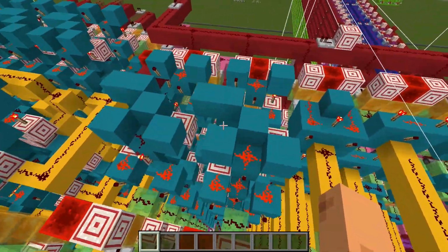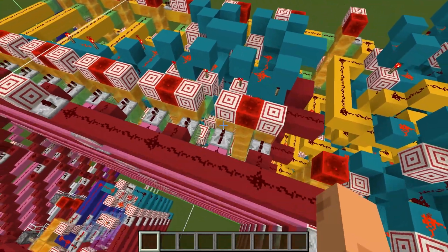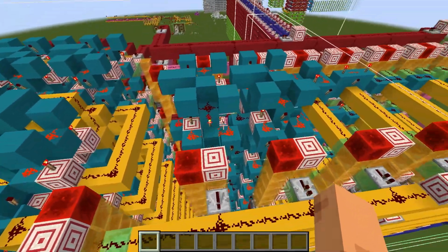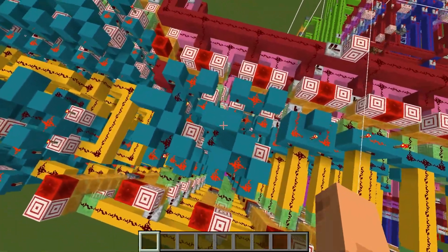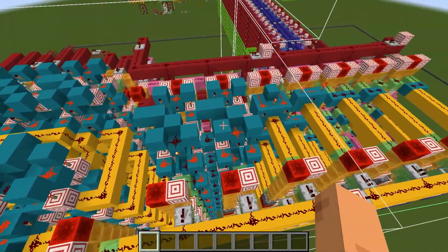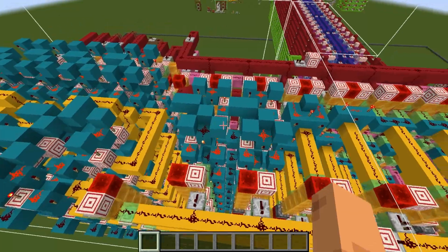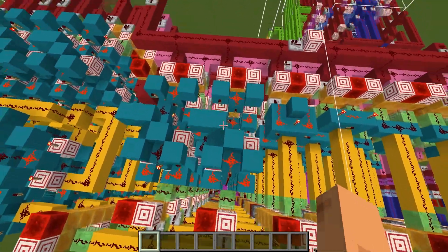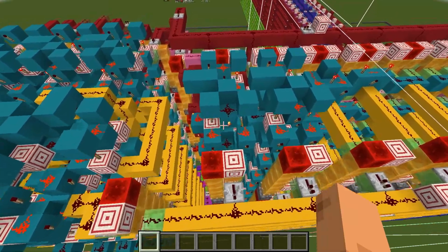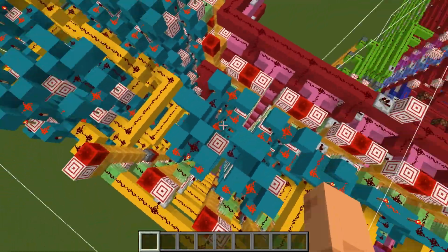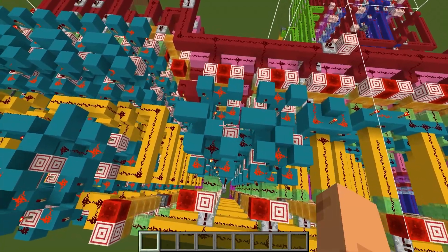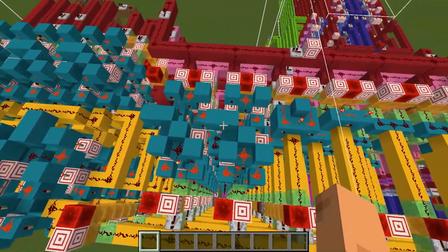I think I didn't combine the 2 into a single unit because it was a little more complicated for the control logic. In a typical CPU, you would combine the adder-subtractor or just reuse the same hardware, because addition and subtraction is really the same operation, just where you negate the second input for subtraction before you feed it into the adder.